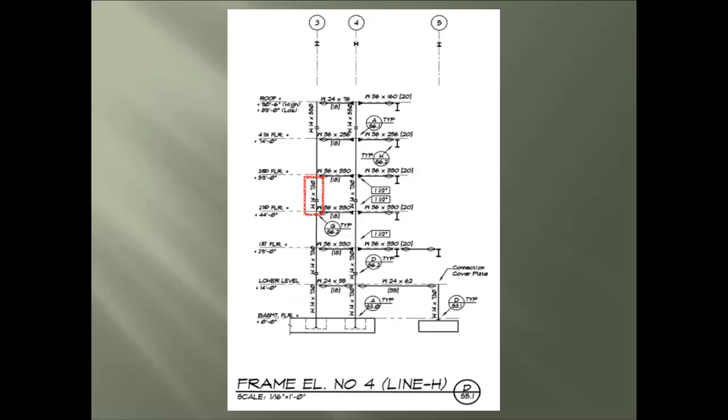We see the column size callouts, and then the beam callouts. Notice the special moment frame and drag strut connections. Here is a symbol for column splices. And lastly is the call out for the orientation of the columns required for the frame. As with the other two views, the elevation view opens a tremendous amount of information.